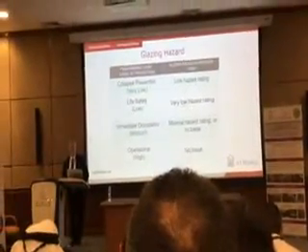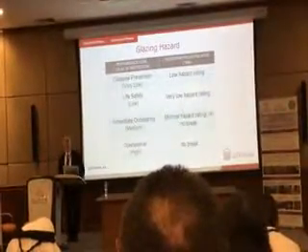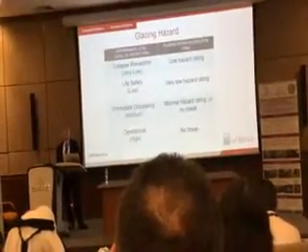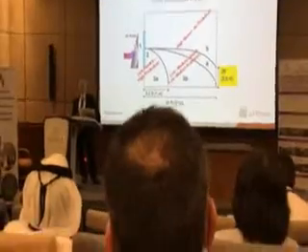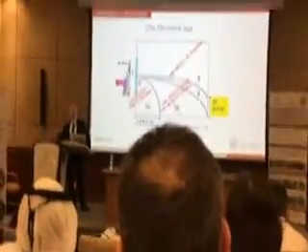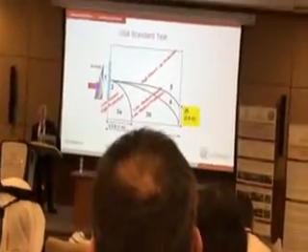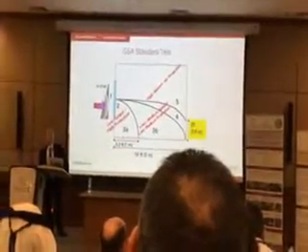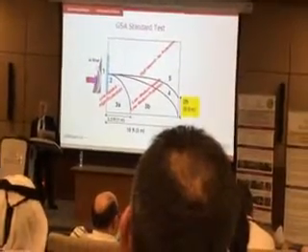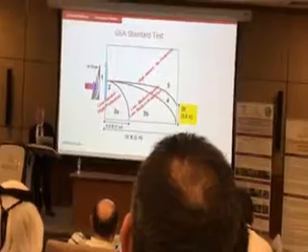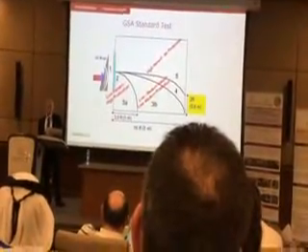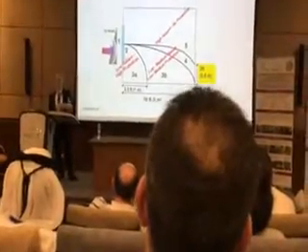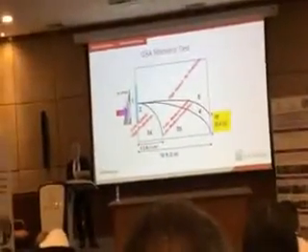Low hazard rating, very low, minimum hazard. How do they talk about rating levels? There are GSA standard tests that qualify windows. GSA, once again, is the General Services Administration. This is a U.S. government agency that looks after government infrastructure. They have a test. This test involves applying either 4 psi or 10 psi pressure on a window, and